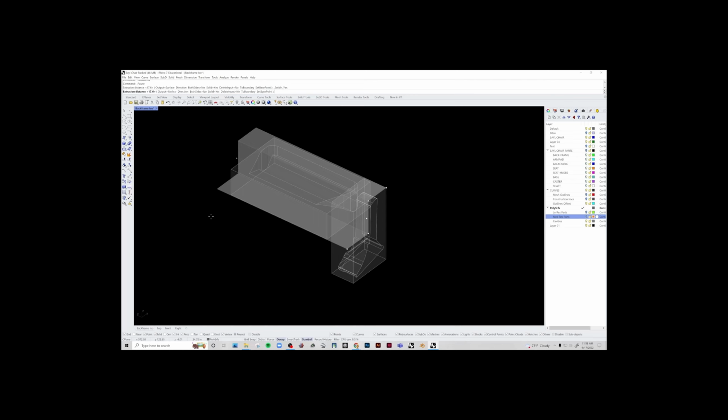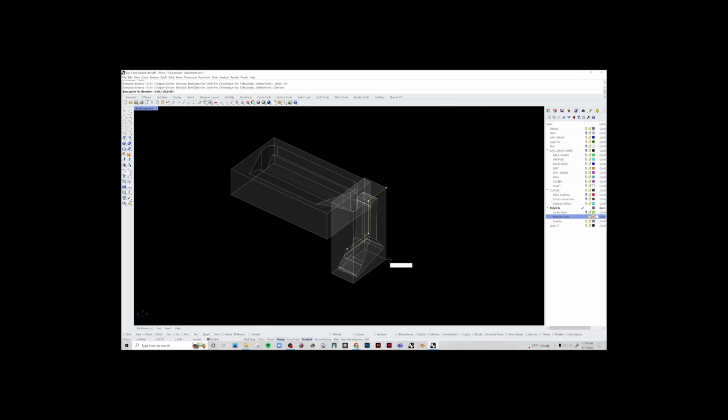And if for any reason when you extrude, it goes in a direction that you don't want, like sometimes it'll still go in the Z direction, you just need to reset that by going up here, clicking on direction, and then establishing the direction. So if I wanted to extrude this, let's say in the Z axis, I would just draw a point.